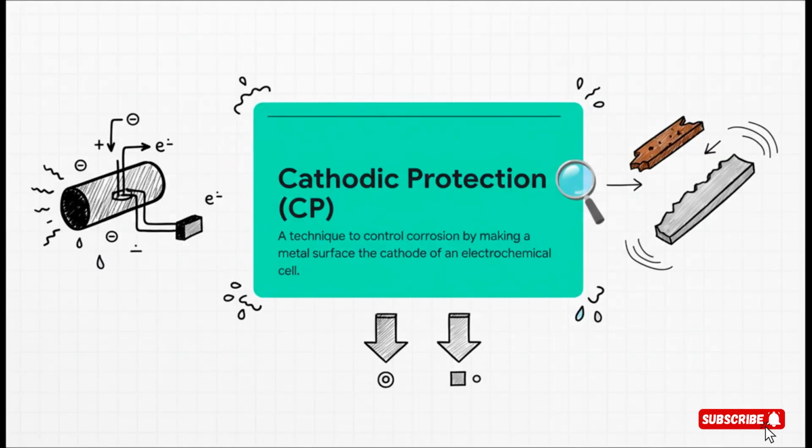So, what's the deal with cathodic protection, or CP as we call it? At its heart, it's an electrochemical trick. Think of any piece of rusting metal as a tiny natural battery, what we call an electrochemical cell. This little battery has 4 parts: an anode, which is where the metal literally dissolves and releases electrons, a cathode, where a different chemical reaction happens, a metal path for those electrons to travel, and an electrolyte, like soil or water that lets ions move around.